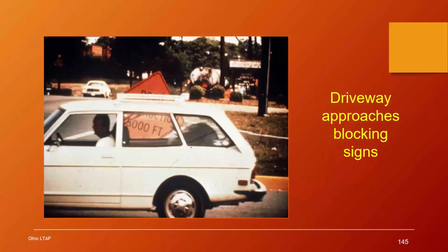If you go back to the title of that table about sign spacing, you'll see that it has a catchy title as well. What did it say? The title of that table is Recommended Advanced Warning Sign Minimum Spacing. And so there's two weasel words in that title, recommended and minimum. So that means that you use your judgment to put that sign in a better location so that the approaching traffic will clearly see it.